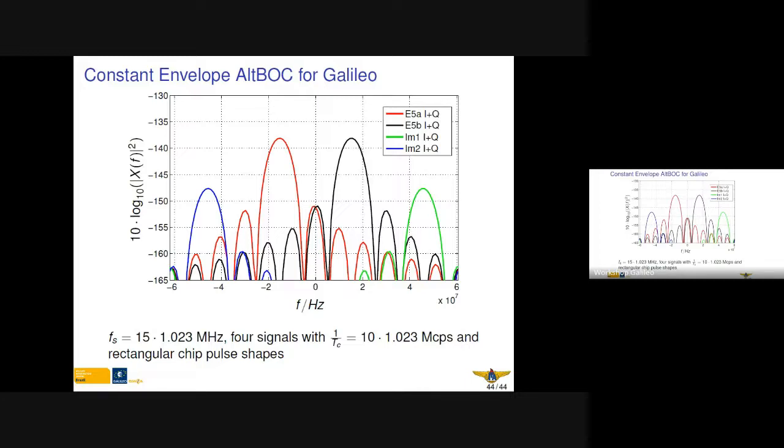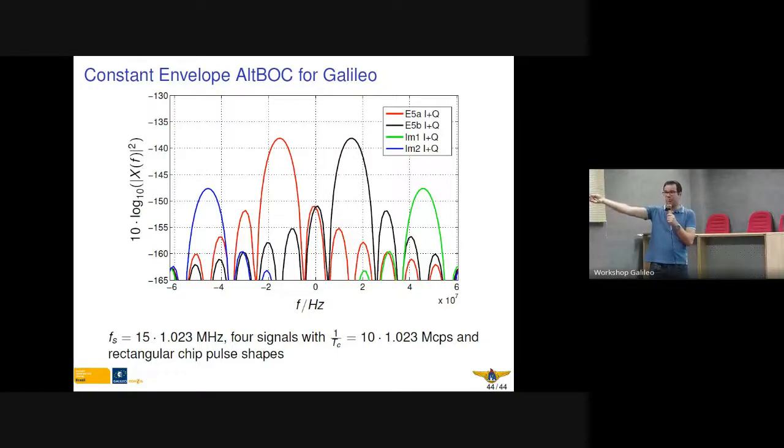So I just want to stress again, these interplexing methods, either interplex or AltBOC or other methods, are only important up to the amplifier. The whole reason for thinking about this problem at all is to optimize the amplification of the amplifier for a superposition of signals. After the amplifier, it's not important anymore, for example, to have these intermodulation products.